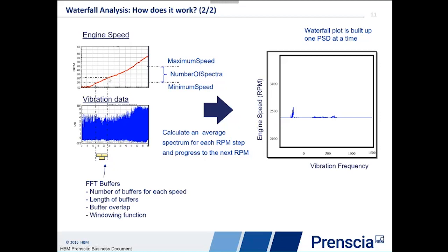Then we continue. We go to a higher RPM value, so to 3,500, say. So that's a new signal I want to isolate, and I want again to do some FFT analysis and extract the PSD or the modulus of the FFT or whatever, and display it again next to the new RPM. And let's continue till we covered our range of speeds, right?